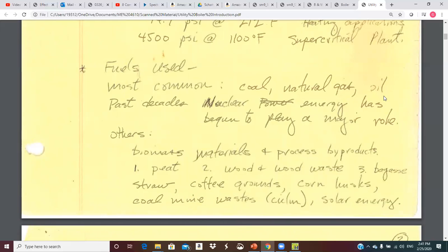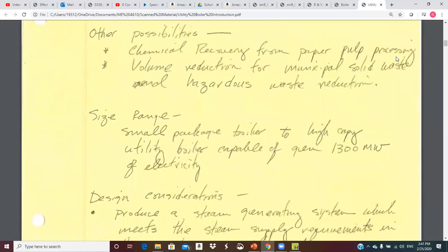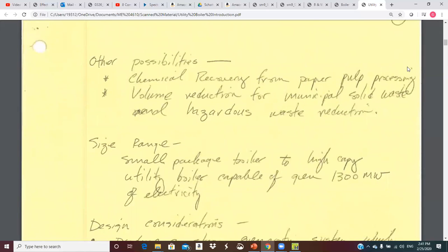And that's another reason why we spent so much time going through Rankine cycle: all of that stuff is just a heat source that can be transferred in to make that steam. And once you get that steam, hey, you're doing Rankine cycle. So it's pretty fundamental to what we can do. Anybody co-op in a paper mill? How many different energy sources did you deal with?